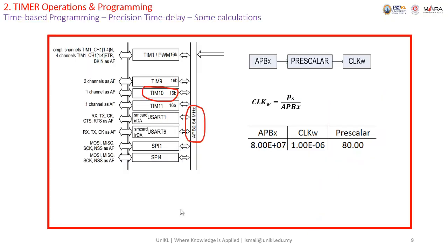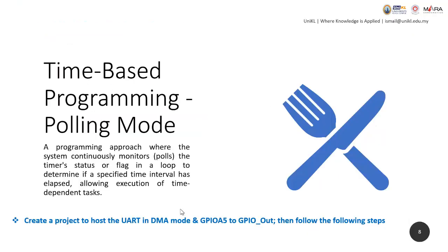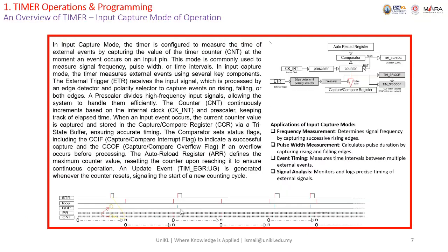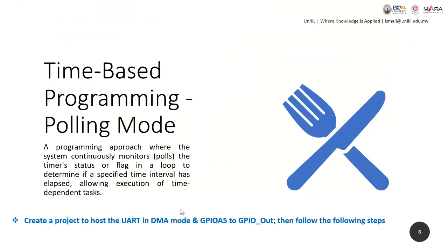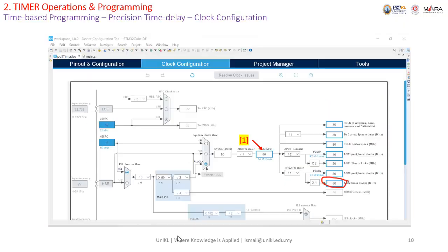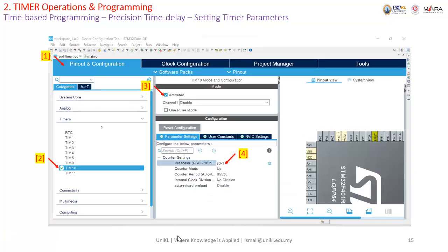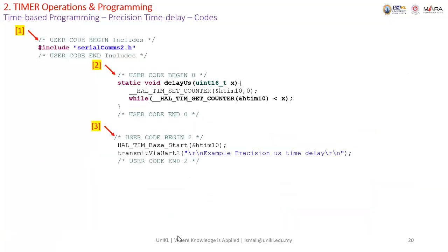Maybe we can see it later. Okay, for time-based programming we can have polling mode and interrupt mode. Time-based polling mode we use for the time delay, as I use it for the STM32.